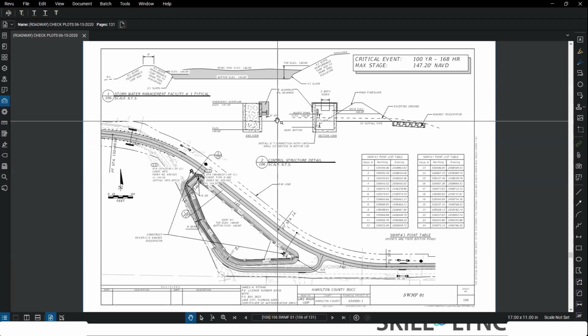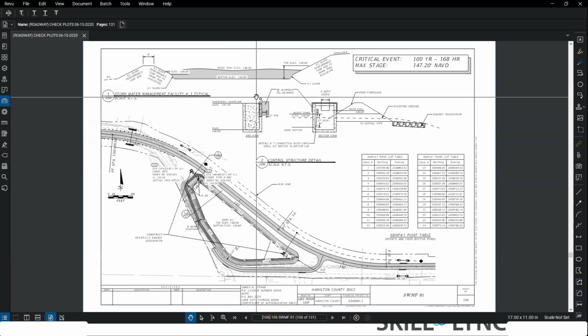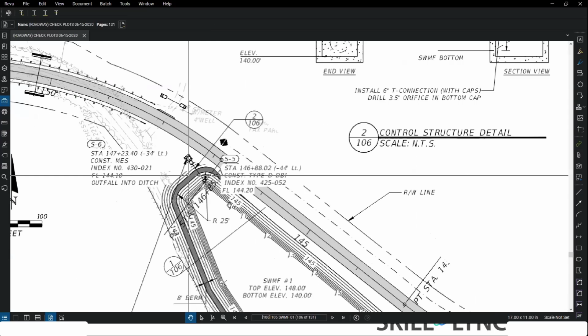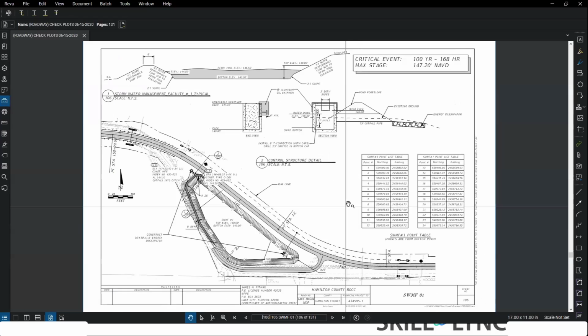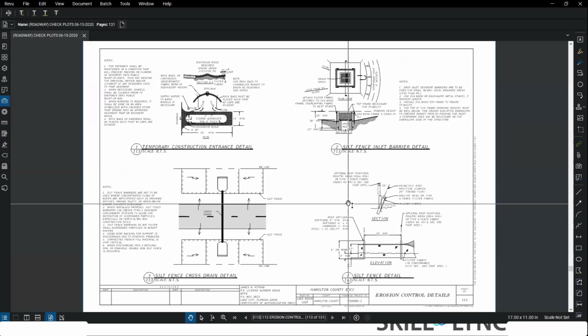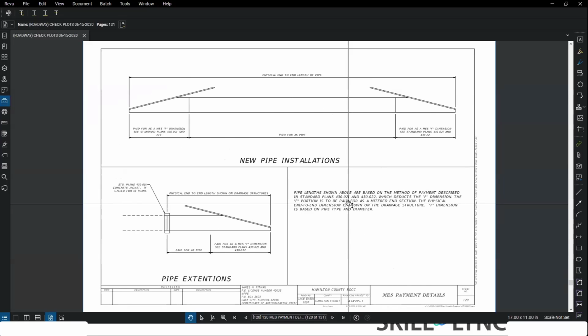There are also dry ponds. The dry pond would be above the seasonal high water table. Dry ponds are a lot harder because they require enough percolation in the soil to let the water drain. Whereas this one here outfalls to a structure, as you can see right here. This is where the outfall structure is, and then the pond just stays wet, so it's not a big deal. And there are notes for the other ponds.